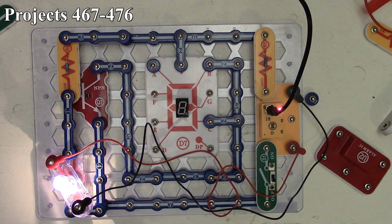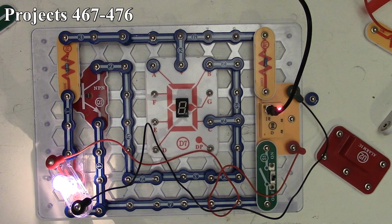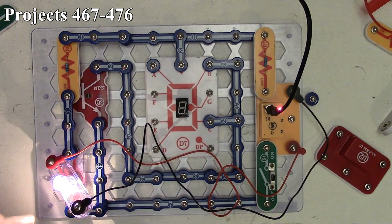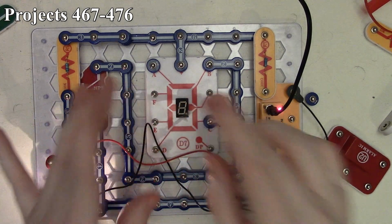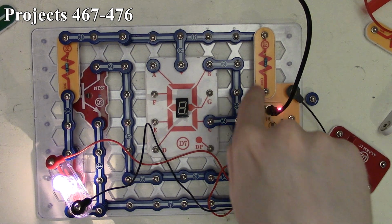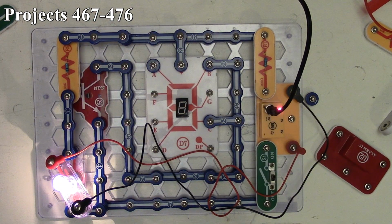but we're also making use of our photoresistor here, which you can see I've got the 6-volt lamp sitting over it so that it reduces the amount of resistance there, because the way the circuit works is that we're taking current away from the base of the transistor there so that it cannot turn on, thereby turning on our 7-segment LED. So by keeping the resistance low on our photoresistor, the current just flows in a loop like this. None of it goes into our 7-segment LED display.